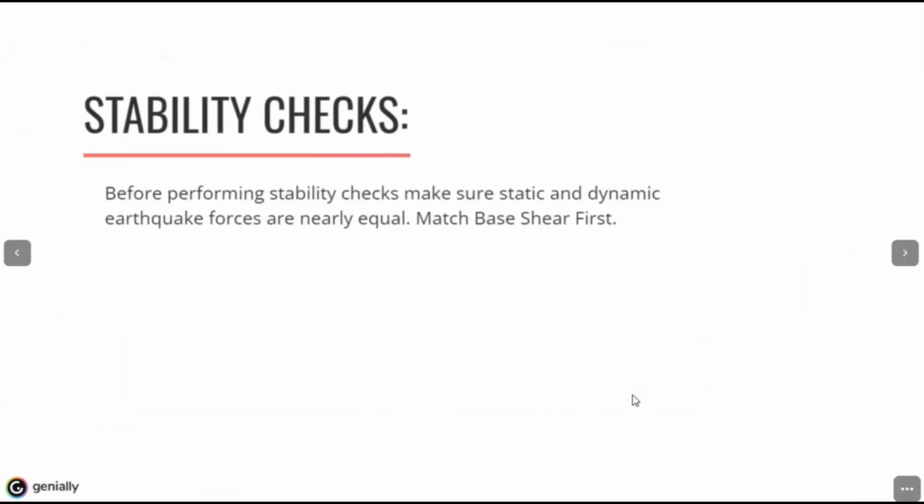So right now, what we will do, we will perform the stability checks. Please make sure before performing the stability checks that the static and dynamic earthquake forces should be nearly equal. So you have to match the base shear.